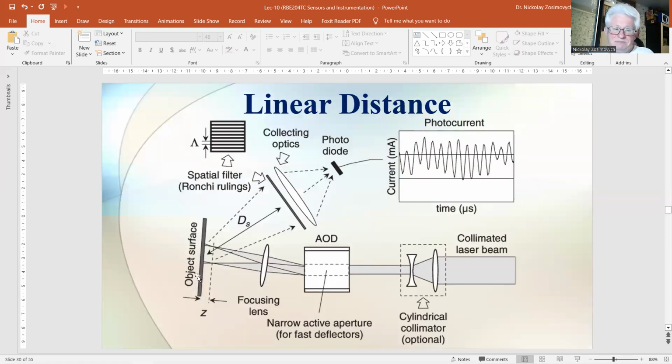Optical sensing systems are widely used for contact-free distance measurement in mechatronics. The major principles, in order of increasing accuracy, are reflectance, triangulation, and interferometry. The reflectance method is very useful for low accuracy applications and binary sensors. The small-sized electro-optical components can easily be mounted on or integrated into mechatronic systems.